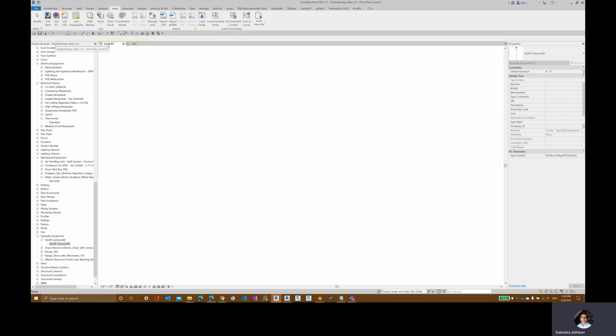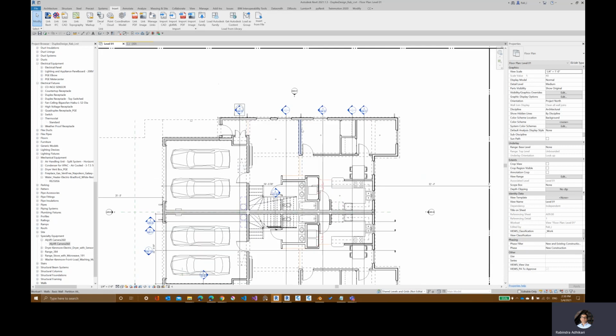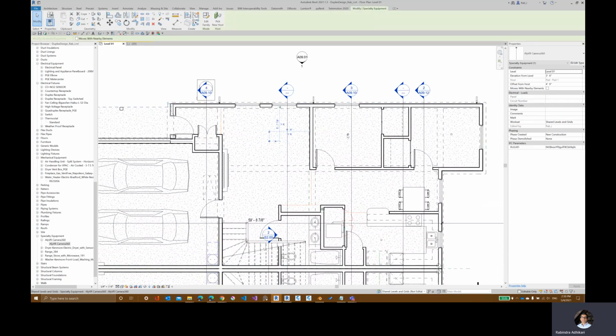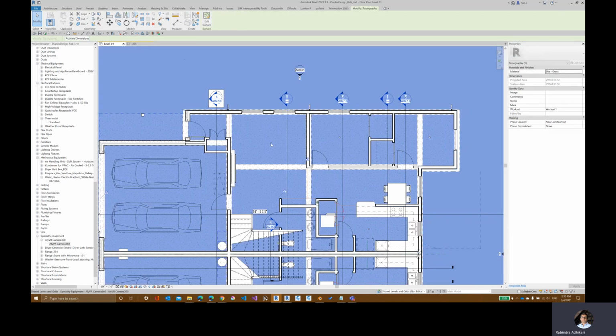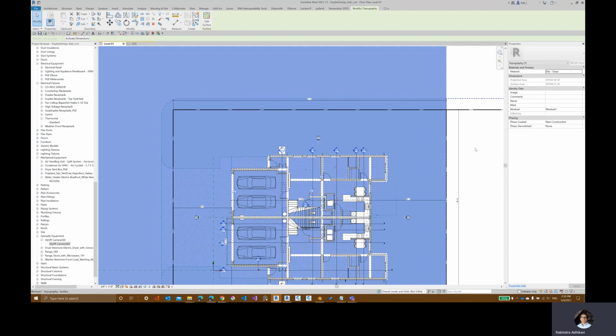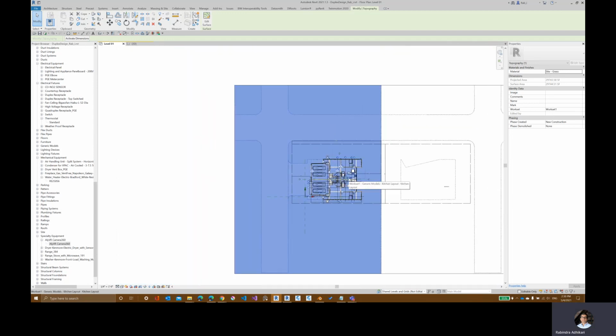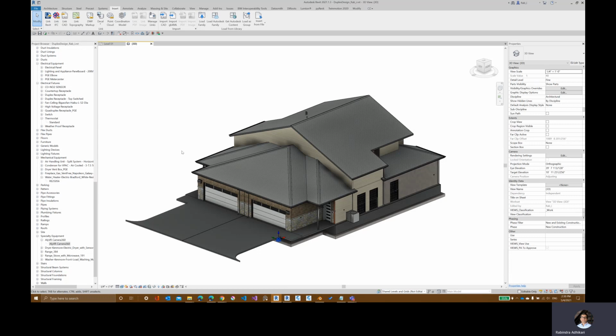In a floor plan view, you can simply populate your rooms with these cameras wherever you want the perspective or the panoramic view to be created. So in this example, I have 4 locations for the panoramic view, which is almost the center of the room for these locations. Once I have those locations determined, I will open back my 3D view and export this view as an IFC.